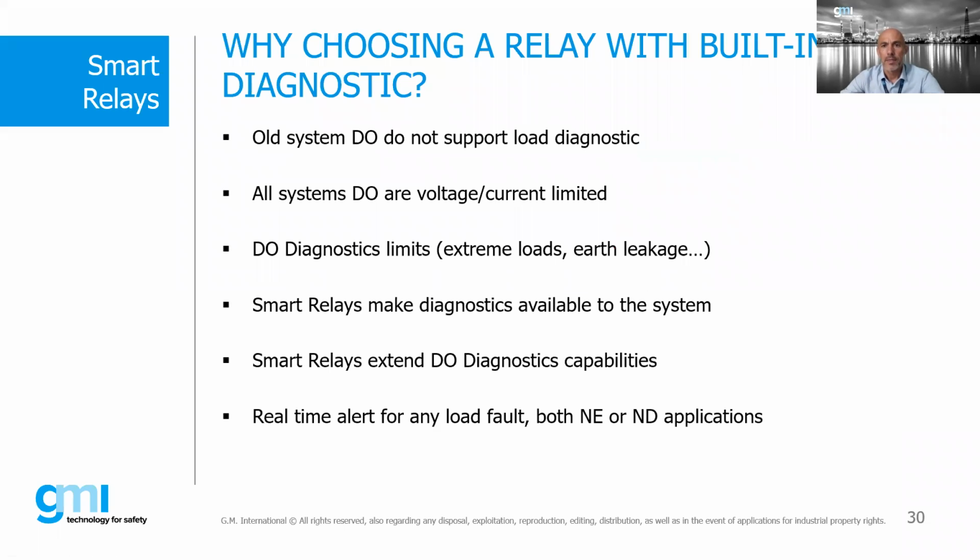Then we introduce another point. So we have seen that one relay inside can fail for any reason. But we want to be able to detect this kind of failure. So why is it important to choose a relay with built-in diagnostic also? There are a few points.